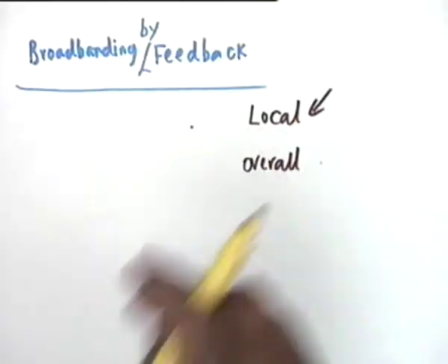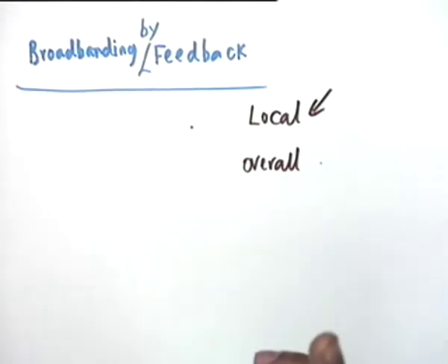And with a single transistor feedback, it is easier to control its stability. If there are three such, how many capacitors do they introduce? 9 of them. C pi, C mu, C0 for each. And you don't know what will they conspire to. 9 enemies, it is easier to fight 3 rather than 9. So, overall feedback is used only when it is essential. Local feedback is preferred.